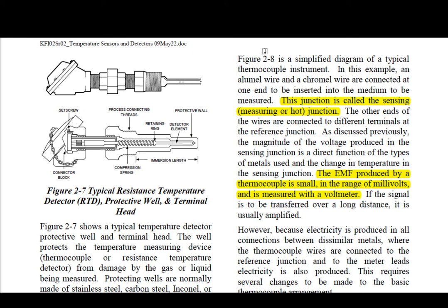And what has been so interesting is that each one of the thermocouples measures a different temperature. And how can that be if they're in the same location on the pipe, so many feet from the reactor vessel, with their probe stuck in approximately 2 to 3 inches? And all 3 are at the very same location, and all 3 are measuring different temperatures. How can that be? The first thing you would think of is, wow, I got 3 thermocouples and they need to be changed out. They are reading incorrect readings, but that's not the case. They've been pulled, they've been tested, and they all are operating as they should.